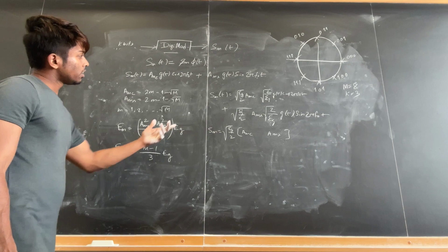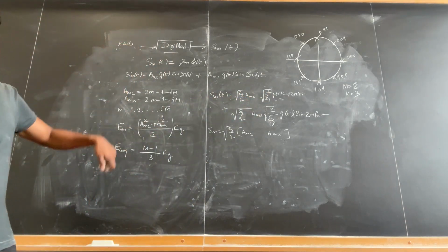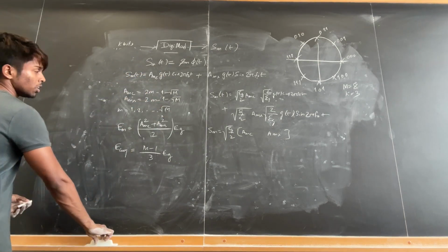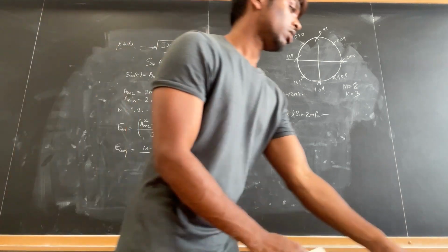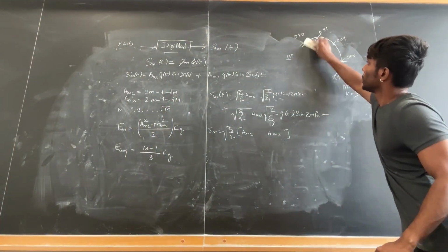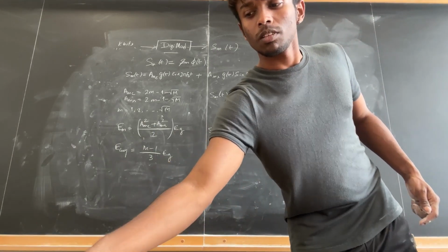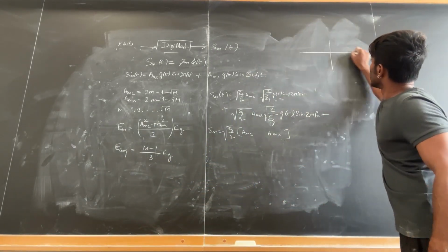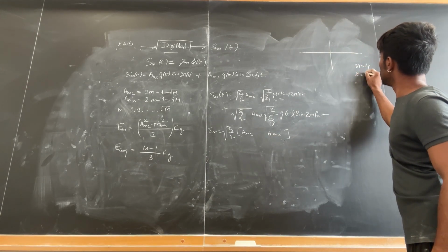So we can see there are two dimensions in the QAM signal also, but it doesn't go in a circular fashion, it rather goes in a quadrature manner, square fashion. So how do we draw the cases for QAM? We have to start at m is equal to 4, k is equal to 2.